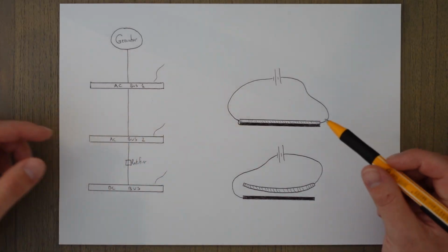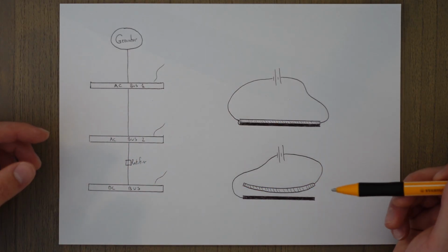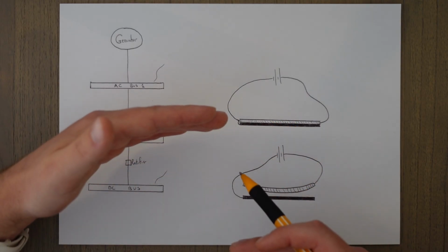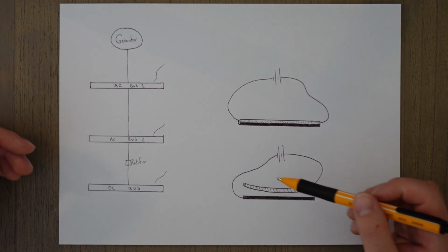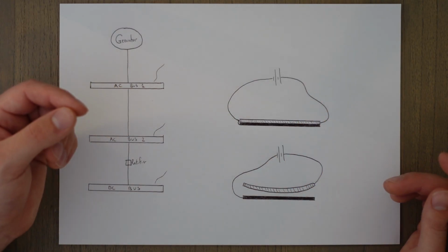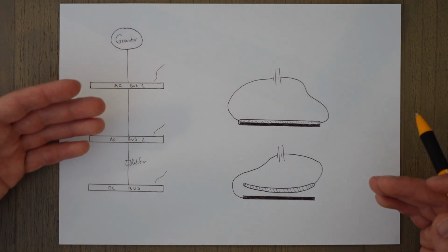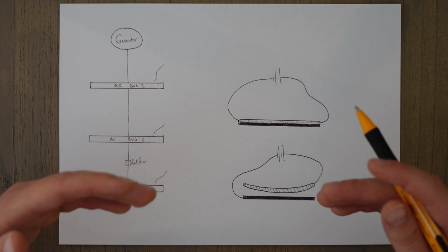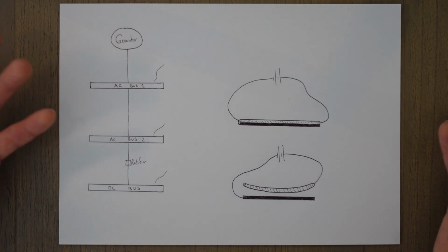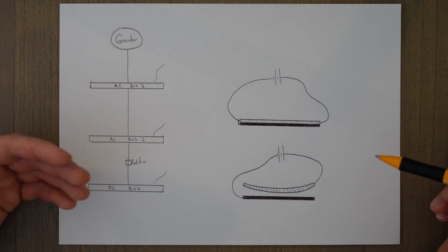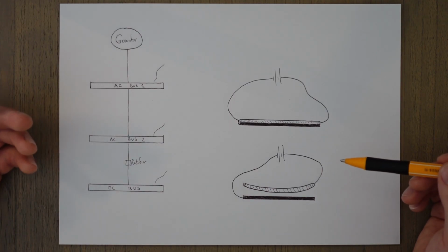When an excessive current travels through the circuit breaker, then the metals will heat up at different rates, expand and separate. The separating metal strips will push on the circuit breaker mechanism and pop it out, and obviously stop the current flowing. The circuit breaker can be reset, but with caution. Why did it pop in the first place, for example? Probably because the level of current flowing through the circuit was unsafe.